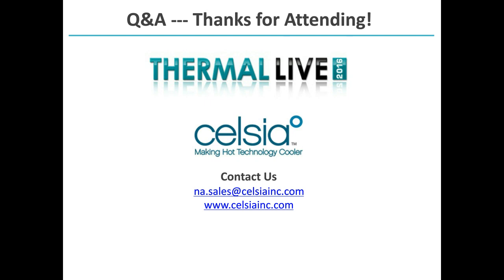Okay. And our final question for today, because we're a little bit over time. This is quite an interesting one. It comes from Tommy, a question on the application in data centers. Tommy says, this is for a data center application. If I have multiple heat sources on the server, can we route heat pipes from various heat sources to a central condenser? Yes. That's quite common to do. You just have to make sure that you have enough capillary action to move the liquid past that first or second heat source to the third heat source. So it's very common.